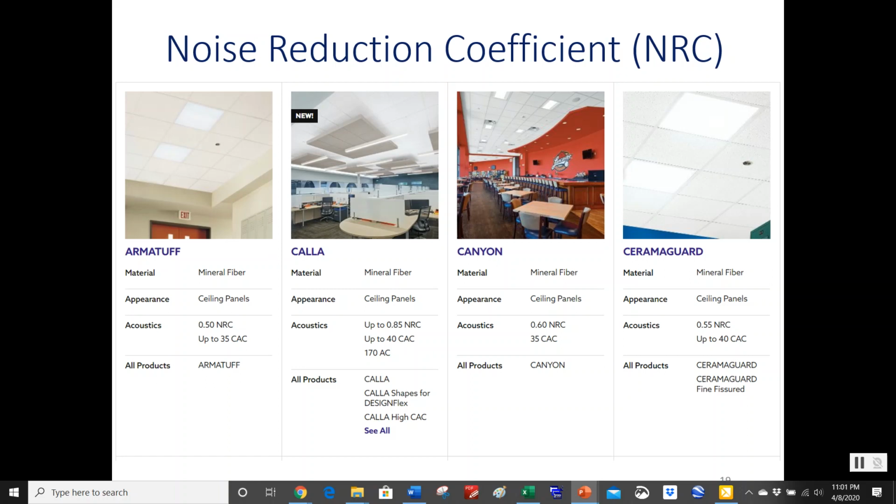In any of those cases where you have a significant noise source above the ceiling, then if you're going to have acoustical ceiling tile, mineral fiber would be better because you get more moderate sound absorption, but you get the CAC, the ceiling attenuation class. This has more to do with sound isolation. We're going to learn about sound isolation; that's coming up next. That's the isolation of sound in one space from another space.